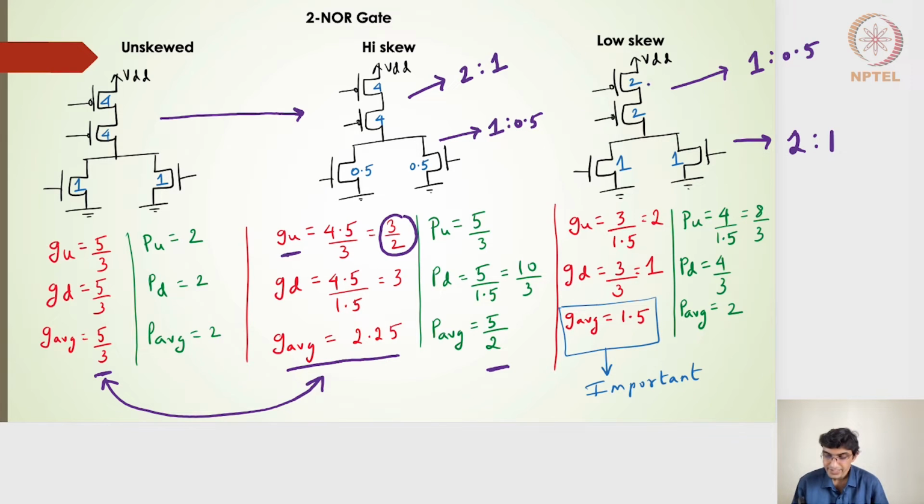In this particular case, the equivalent transistor for the 2 transistors in series will turn out to be the size of 1, and that's why we have the benchmark inverter size as 1 on the PMOS side, and thereby the NMOS side benchmark inverter size will be 0.5. So hope this is clear. Now if I have these benchmark inverter sizes, the logical efforts for going up will be nothing but